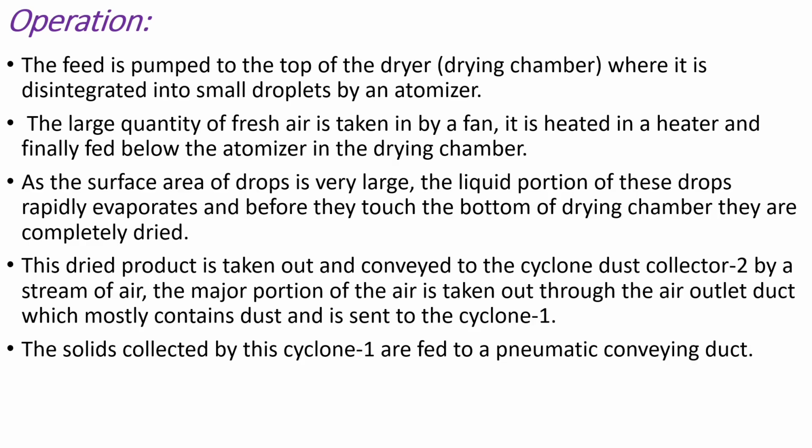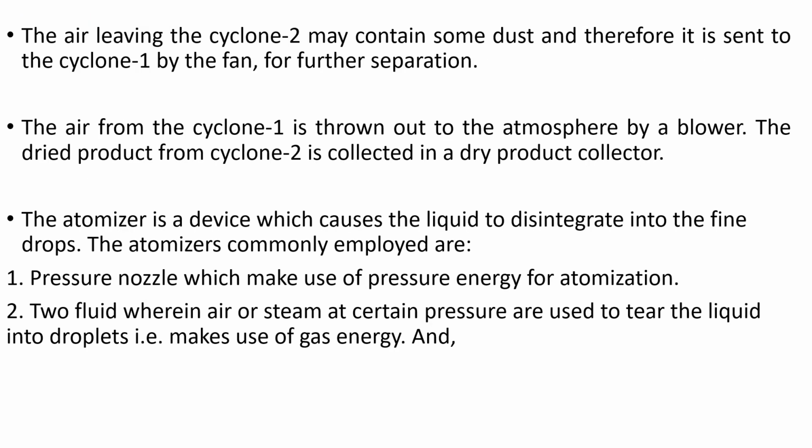And we have almost 4 advantages of spray dryer. It is very fast drying because it occurs in seconds, and it is continuous operation, so it is suitable for large scale production, produces fine products, powder, and it is suitable for heat sensitive materials.